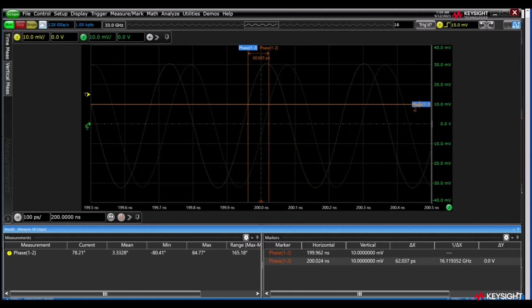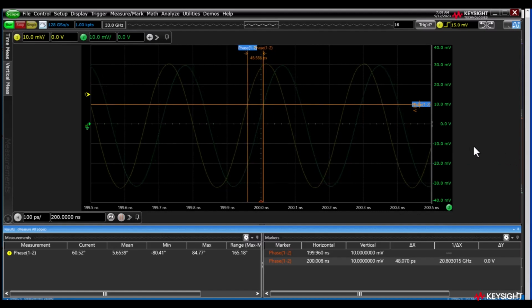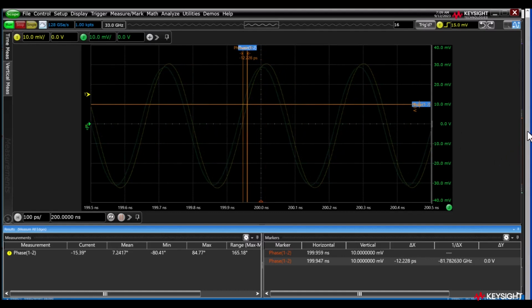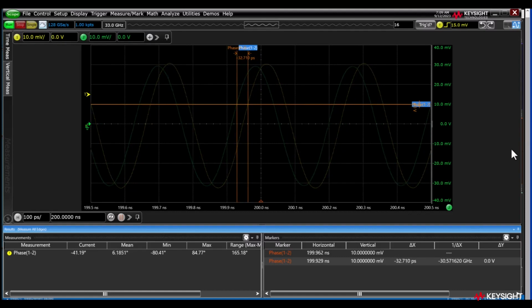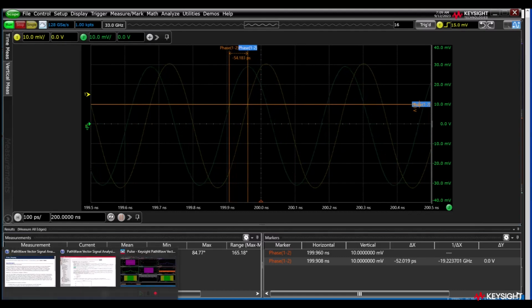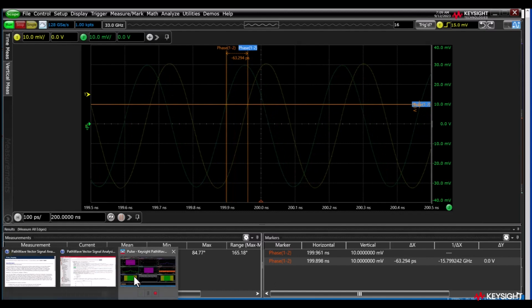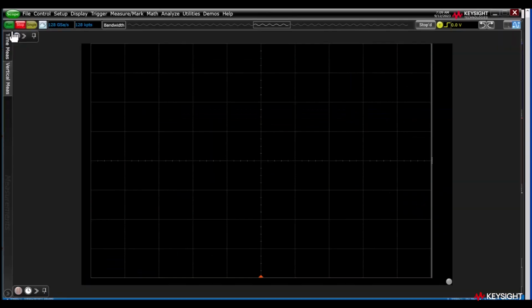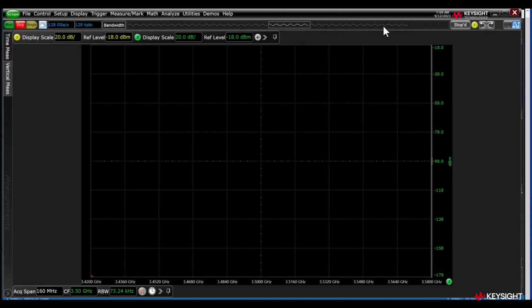All right, well, what we can do is feed this into the VSA software and be able to actually calculate out what is that azimuth. In this case, we're going to have a couple antennas being simulated as if they were side by side, 1 lambda spaced. So let's go to the VSA software and let's hit run. And what you're going to see is a capture of the, let's shrink this down.